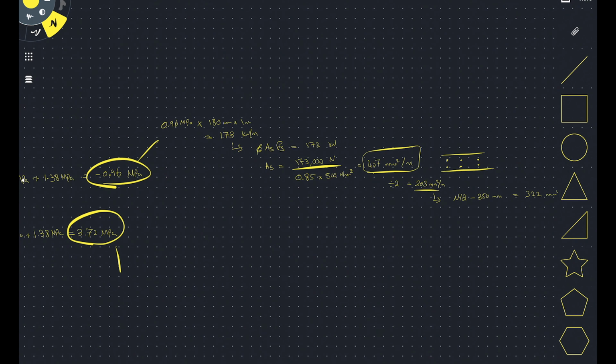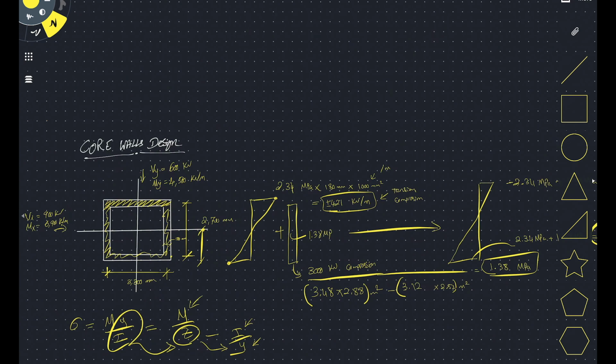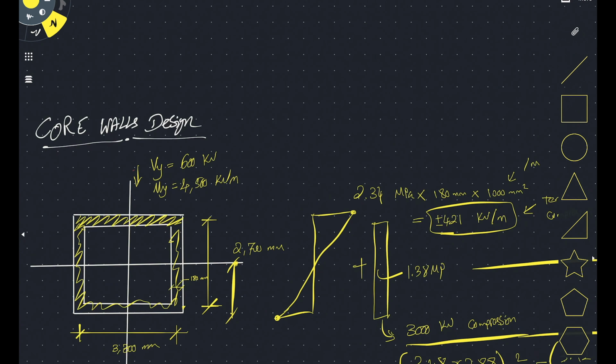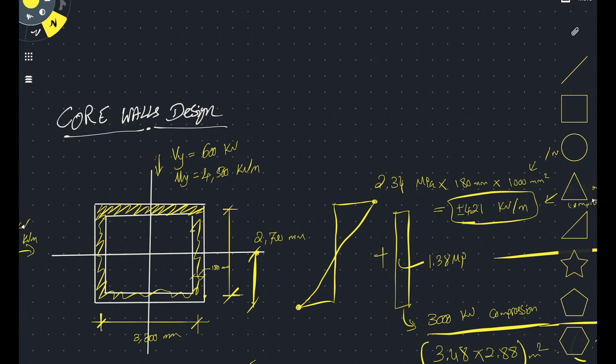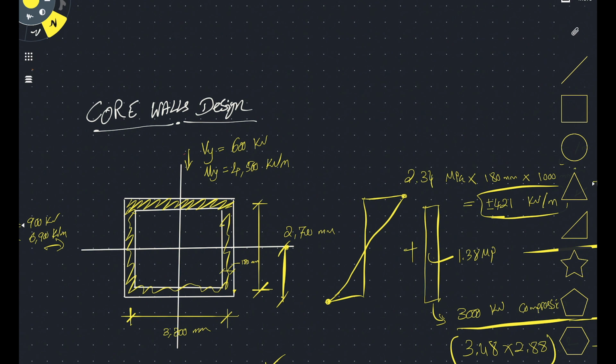So there we go, we've designed the tension force at the flanges, and we are assuming it's reversible. So this 4500 can be going downward this way, or it can be going upward this way, assuming it's earthquake or wind, and it's a fully reversible load case. So we'll need to put this reinforcement in the top flange and the bottom flange.